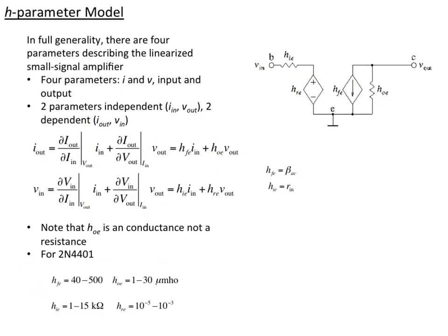That's given that we have 5 to 15 volt sources on the collector, and we'll want milliamp currents on the collector. The output conductance is typically measured in micromhos, and the reverse voltage is typically very small. So again, we have already been using the input resistance and the gain, and there's just two more parameters that we might consider.